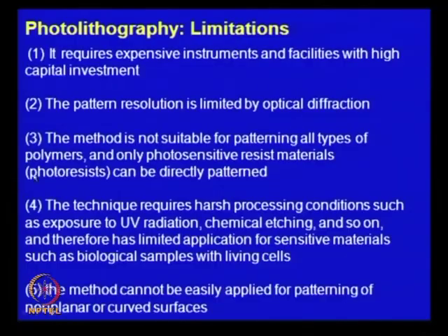The pattern resolution, which we talked about in one of our earlier lectures, is limited by optical diffraction. So, depending on the wavelength of light, you cannot really go below a certain critical lateral resolution, irrespective of the feature size on your mask. The method is not suitable for patterning all types of polymers. This I guess you understand by now.